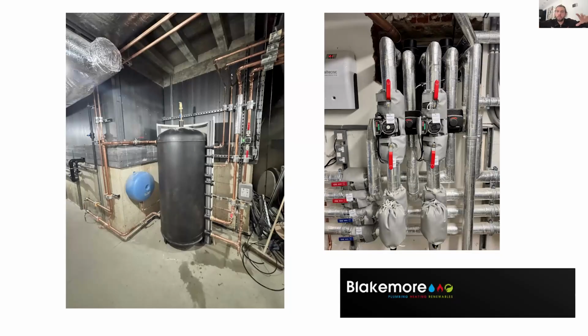So we've got 42 mil lines from both heat pumps through. Pumps are on the returns going back. ESBEs are on the floor there. They're the VRG 131s, the 1.5 ones. We wanted a good KV value on them, and something that would divert well. We've got the Calefi XF at the bottom, which are 1.5 units, which you can also set your KV value on, so you can use them as part bypass.